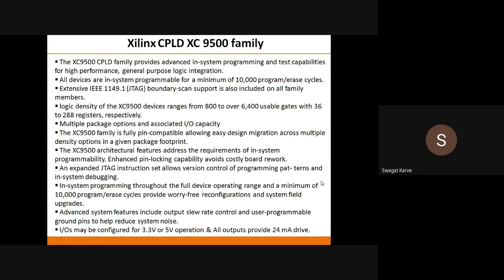Okay. So what we have discussed in the last lecture is the Altera Max 7000 CPLD, right? And the architecture of its different blocks, right? So again, I will summarize it in brief. The basic CPLD structure has three important blocks: the I/O input output control block, then the LAB, that is the logic array block, and the programmable interconnect array, that is PIA, right? And this PIA's role is to connect each LAB with each other along with the input output control block.